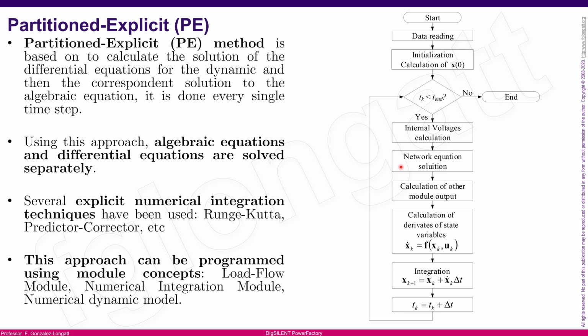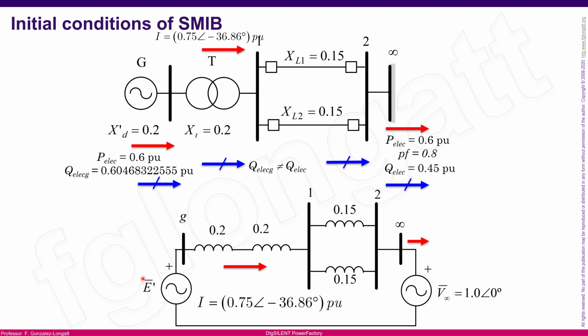In this case, we are using the voltage behind the reactance, and that is the simplest model that you can find. If you are using the seventh-order model, or any model as complex as the one typically used inside PowerFactory, of course you will have more state variables that you need to know. Okay. Well, the job now is to calculate this internal voltage.